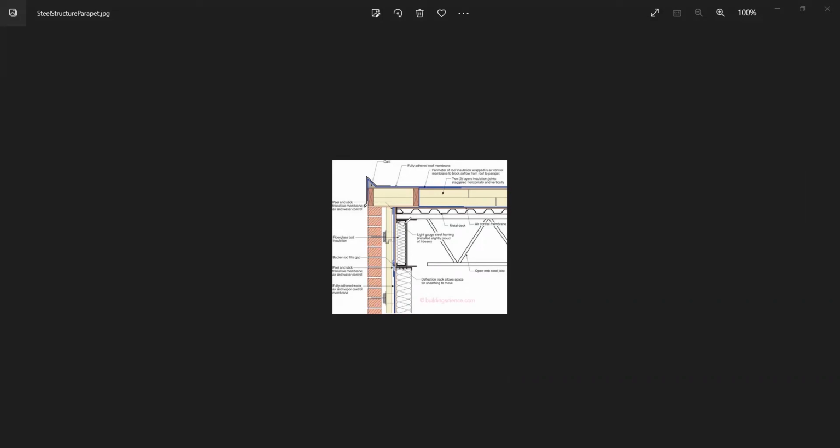And somewhere down the road here, at the end of this beam, it's attached to a column. That column is going to go all the way up to this level, and the beam will be framed into it. So the top of our column will be at the same height as the top of the wide flange steel beam that's here.